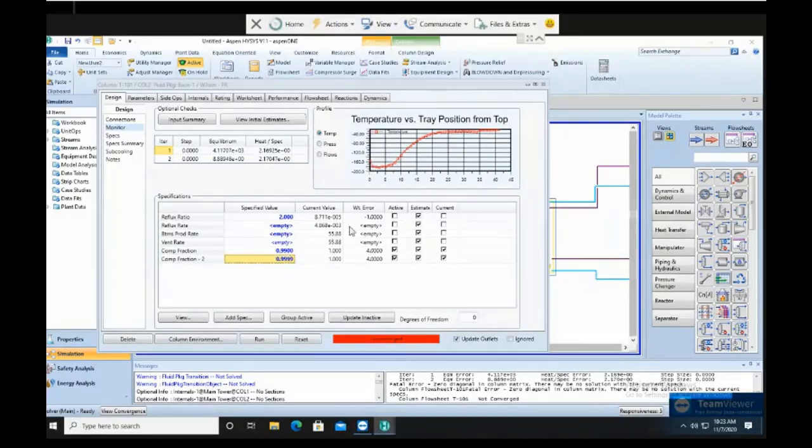But do you see your reflux ratio has become illogical, 1 times 10 to the minus 5. It has become illogical, so you cannot actually do this. Okay, let me change this. 0.995. I want it to be reset.